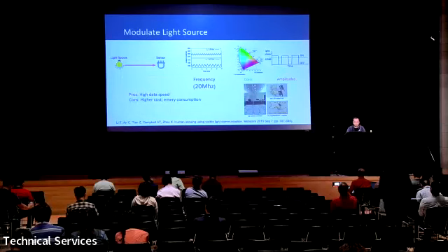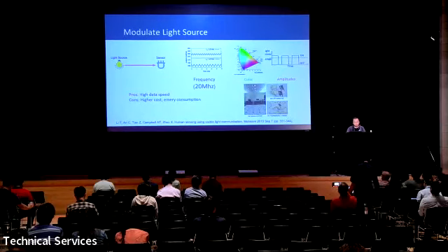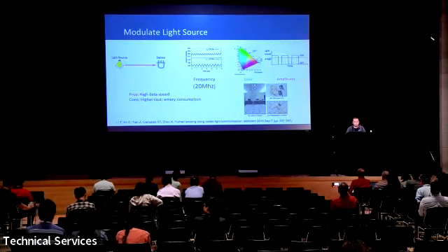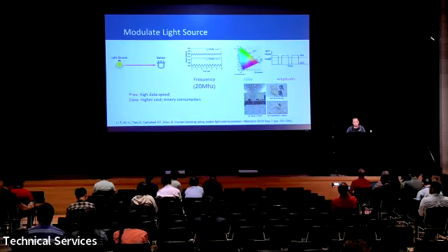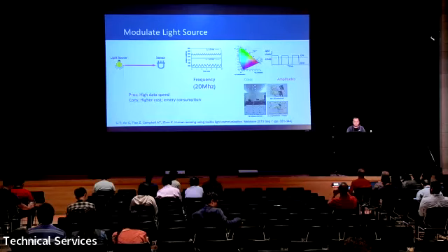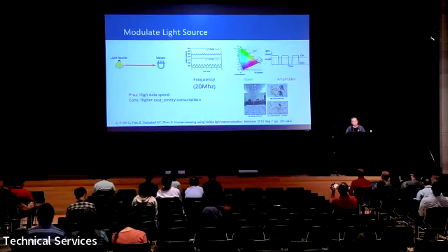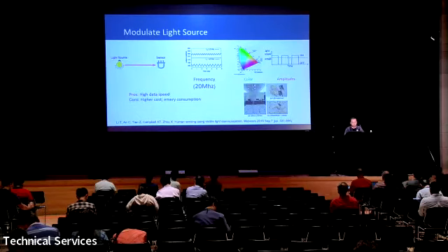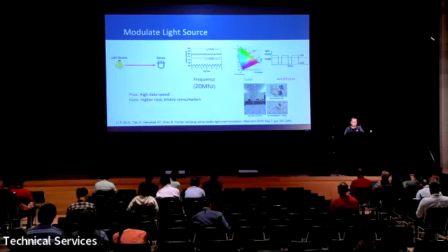So modulating the light source has some good advantages. For example, it has a high data rate. The reason is that because we are controlling the light bulbs, we can control their color and amplitude. Most importantly, we can switch the light bulbs very quickly, like 20 megahertz. It also has drawbacks, because if we want to control the light bulbs, we need to install external drivers. Also, switching the light bulb will cost higher energy consumption. So can we do something about these drawbacks?